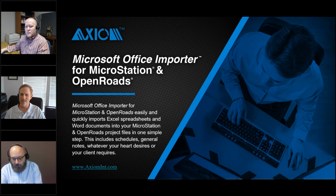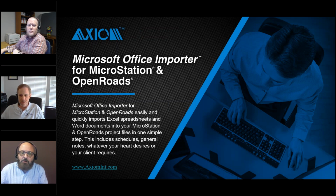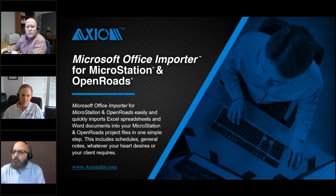But Dan has actually spent some time and did a couple of really cool presentations that I'd love to show you. Dan, are you ready for us to dive into number one? I'm all set, ready to go. That's right. The first one that we're going to be doing, Dan, is the presentation on horizontal reports. Did you want to speak to that for a second? So we're going to show the horizontal alignment of a 26-mile roadway, and quickly generate a report out of that, and then bring that back into MicroStation via the Office Importer. We'll show you a little bit of the design first in OpenRoads, and then show you how easy it is to access any sort of report via a spreadsheet type format, and then of course use the Office Importer tool to get that data back where we need it, whether it be plan view, profile view, or in the sheets eventually.